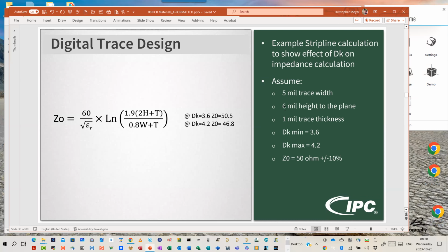So I go to the next higher mil and so on, or dielectric thickness here, right? Height to the plane. I might have fabricators say, yeah, I can't do 3 decimal places of dielectric thickness. I can do whole integers of dielectric thickness, or whatever the case is, or 1 decimal place, and so on. So based off of what your fabricator says, I typically target about plus or minus 1 ohm from my true desired as my acceptable, right?